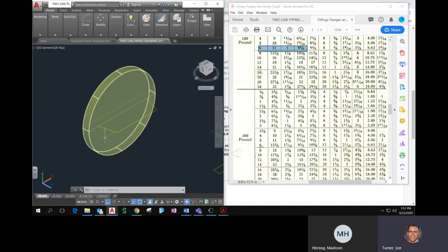The next thing I could do to draw this welding neck flange is use that loft tool that we just learned how to use. So I'm going to draw a circle. I'm going to snap on that surface of my flange, pick the midpoint, and snap to where that 4 1/4 inch number is for that side of the welding neck.